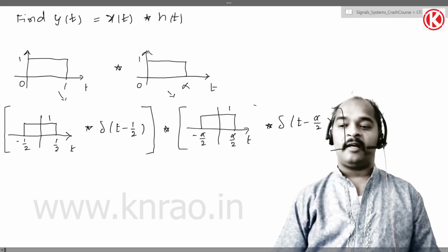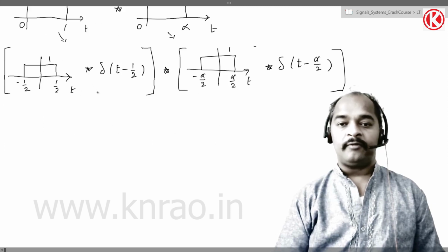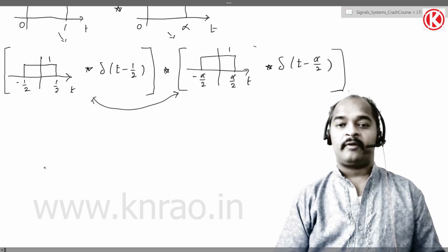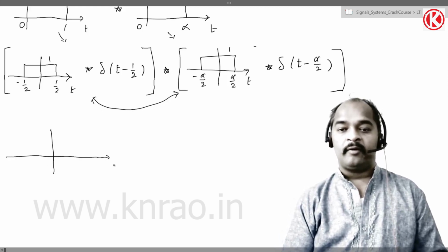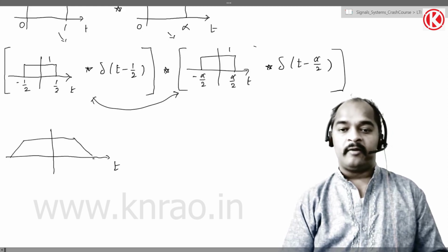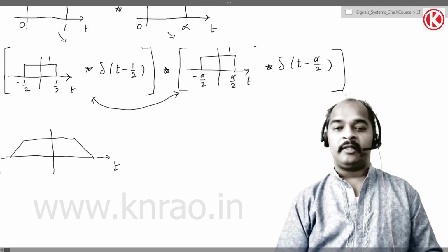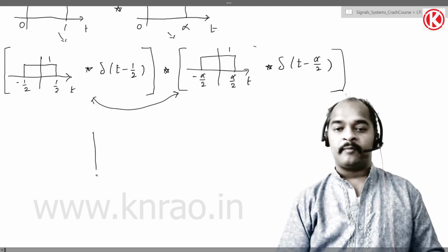Now by using our properties of associativity and commutativity, let us convolve the two rectangles. So what do you get? You get a trapezoid. From where to where? That we already know. This would be minus t1 minus t2. I will draw it a little bit bigger.